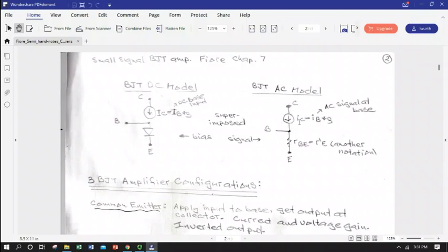Important things to remember about current sources. They have almost infinite impedance. So if we're ever looking at defining input or output impedance, and we're looking at a signal possibly traveling through the current source, we can assume they're an open from that standpoint. So that's an important characteristic we'll use. And then here's our inverse slope of the current voltage curve from our diode equation that we just defined on the previous page. So it's taking the place of this diode.